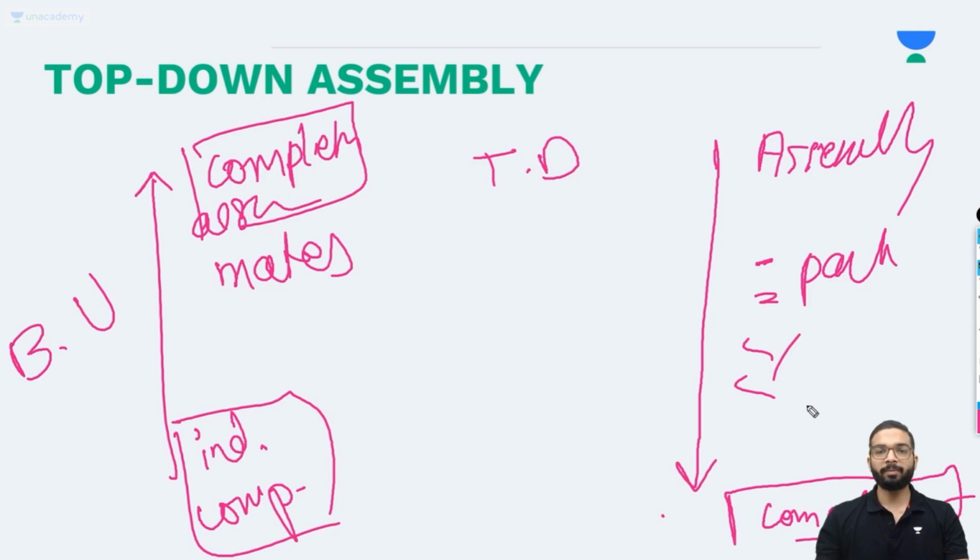Okay, so I hope the basic difference between both these approaches is clear. Here we have our individual components ready first, and then we move to the assembly mode and add them, give them mates, and then complete our assembly. Here we don't necessarily have all our components ready. We have a simple assembly and then we create new parts in the assembly itself. But talking about the top-down approach, it is kind of a theoretical approach.